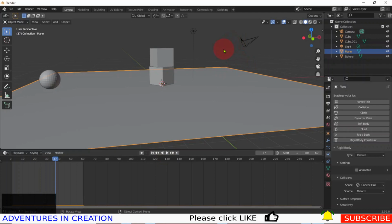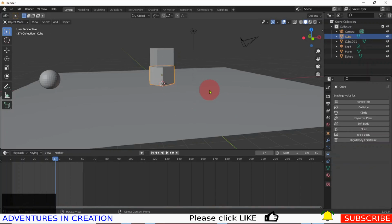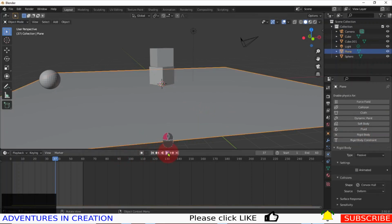Well, first things first, we got to make the cubes have some physics as well. So we're going to click on that cube, make it a rigid body, click on that cube, make it a rigid body. I'm not going to touch anything else in the rigid body part. So now if I run, those cubes shouldn't move anywhere because they're already sitting on that plane and they're sitting on top of each other. So gravity's not making a move. The only thing that's moving is the ball through gravity.